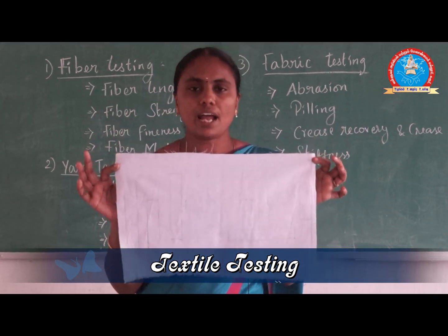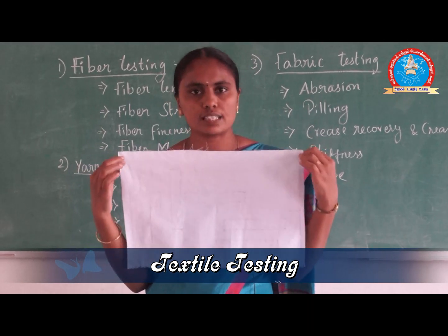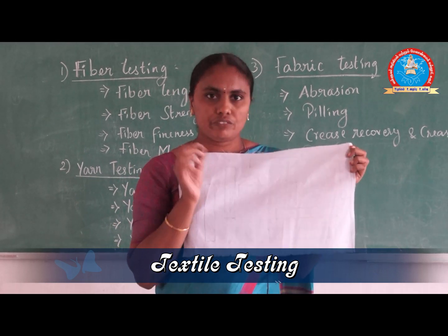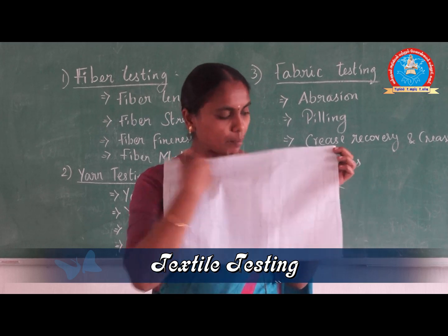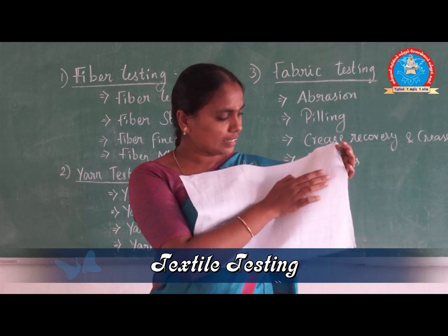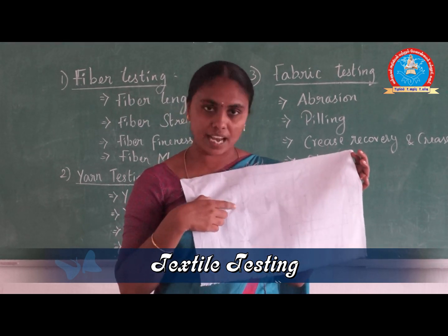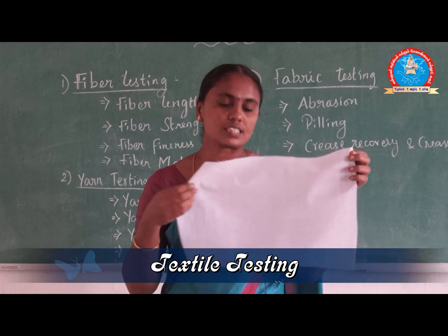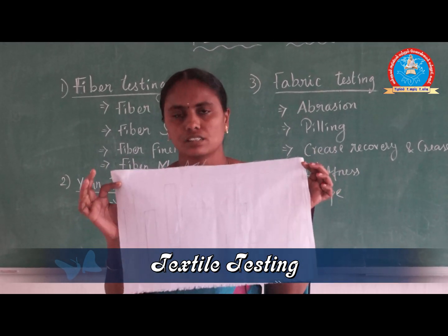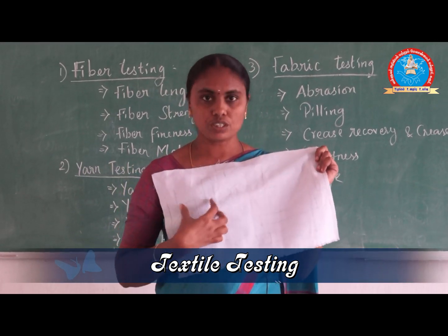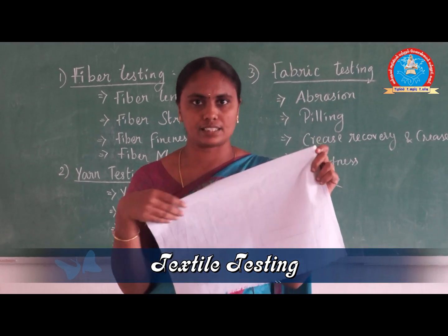We should remember one important point before we prepare the samples. What is that? We first keep the measuring tape and mark the point for one sample, and then we mark the next point for the other sample like this, because if we choose randomly, we will not get a good, desired result. Like this we prepare 4 weft samples and 4 warp samples.